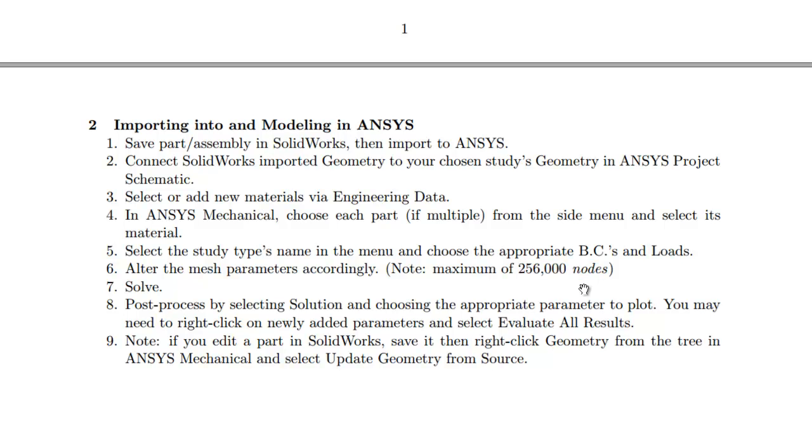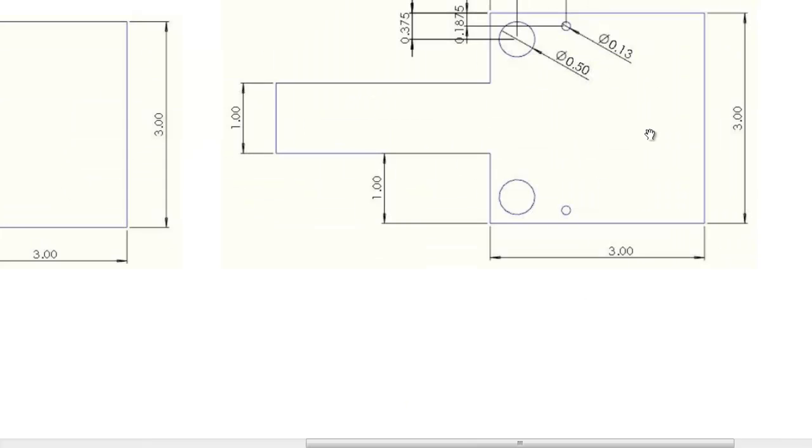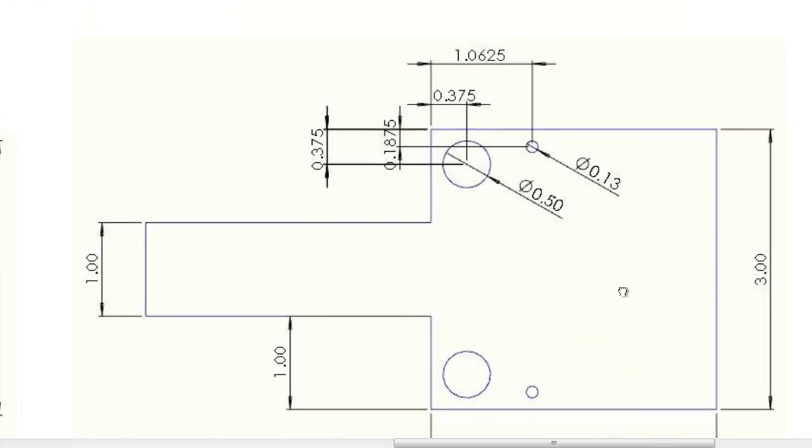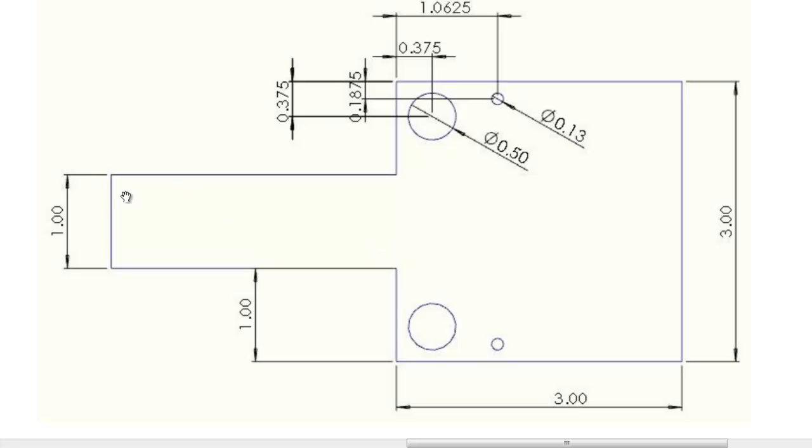All right. So again, feel free to look at these. I'm going to zoom in here, get a better idea what we're looking at here before we jump into SolidWorks. So we have the overall structure of the main one that was looked at up top. We want the 0.1 inch radius fillets here. And then we have two holes, relief stress holes here and here. And so I'm going to basically exploit the symmetry we have in this. So draw this top half, this being the symmetry line here, and then we'll mirror image across with that.